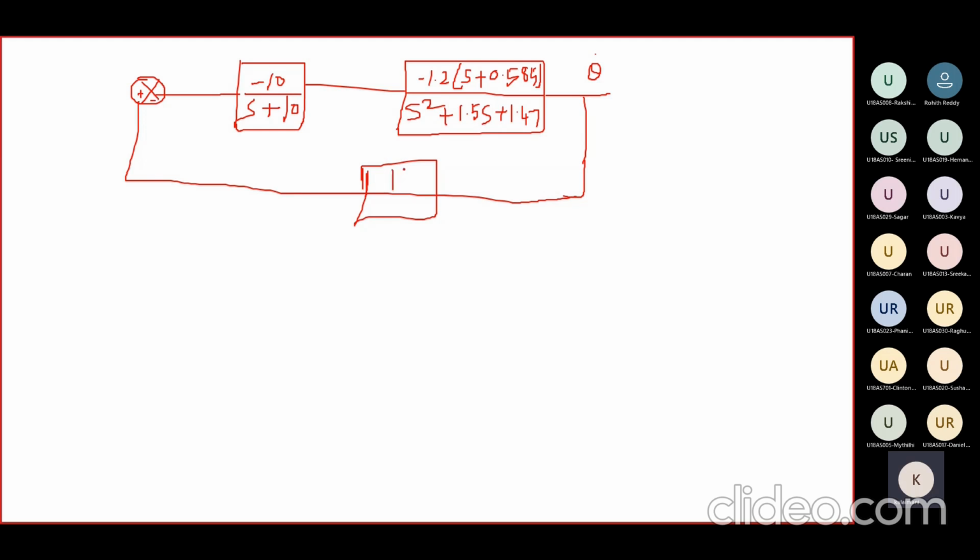That means we use the symbol K instead of s, because here we are using the transfer function times s. Therefore, we need to avoid this confusion. I make it a K symbol for the rate gyro sensitivity. So we try to sketch the root locus for the inner loop. Here the input is the elevator deflection angle, and here it is theta dot, the pitch rate.